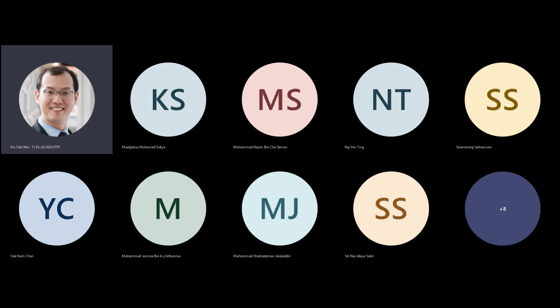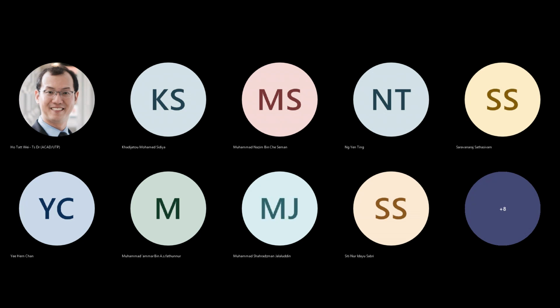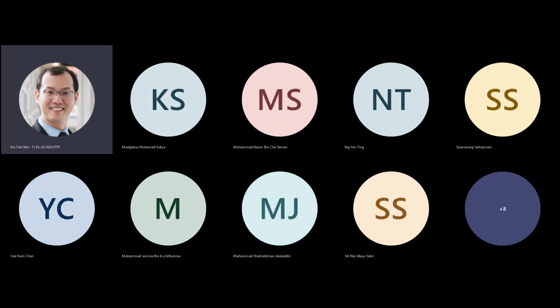And typically the sort of dimensions we're looking at, roughly speaking, this is known as L and this is known as W. So the length of the transistor is the channel length. This is given by L, and typically this is the smallest number in the process. If it's a 7 nanometer process, this is roughly 7 nanometers. If it's a 0.180 micron process, this is 180 nanometers. And this width is a parameter that the designer has some degree of freedom to control.